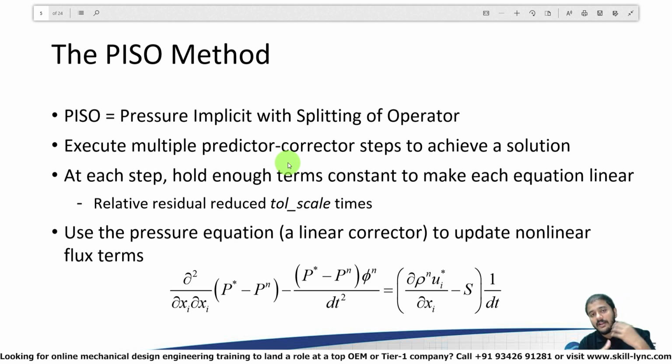So when you're starting out with your CFD calculations, when you start out with an initial condition for pressure, there is no guarantee that the velocity that's computed with that pressure will satisfy continuity. Now remember, in the momentum equation, pressure is on the right hand side. So initially you're guessing that. And with that guess value of pressure, you're getting a guess value for velocity, correct?